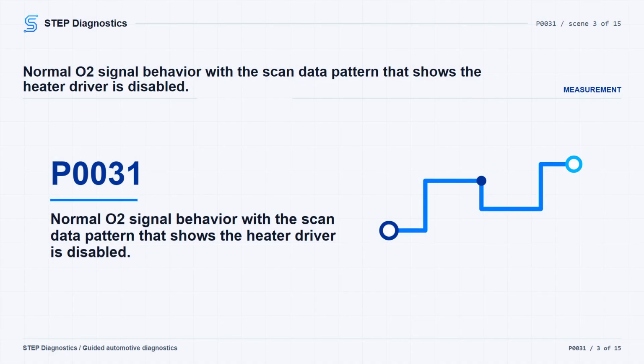Before testing the heater circuit, it helps to understand what the PCM expects to see from this oxygen sensor system. Normal range of the O2 sensor output is a 0 to 1.0-volt analog signal when the sensor is within the normal operating temperature range. If the sensor's reference chamber is contaminated, a negative offset output of up to -1.0 volt may be introduced. Each O2 sensor return circuit has a 2.5-volt bias added, so the bias signal voltage should switch between 2.5 and 3.5 volts on a normally functioning sensor.